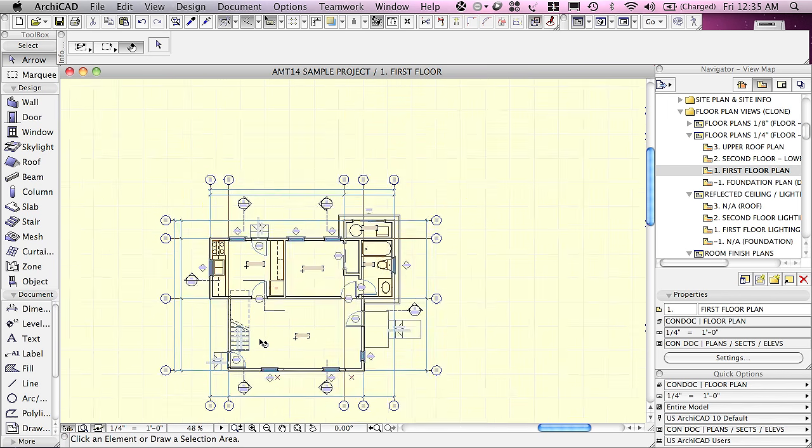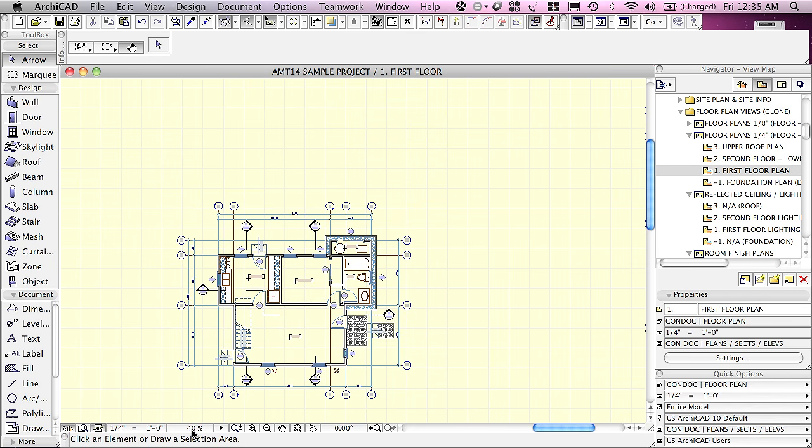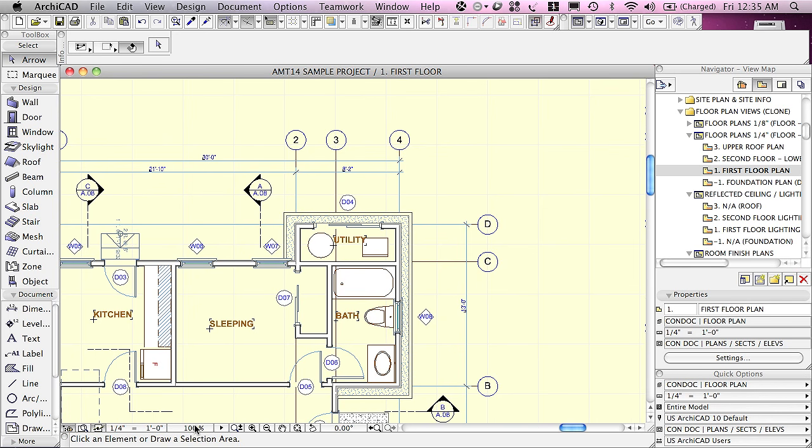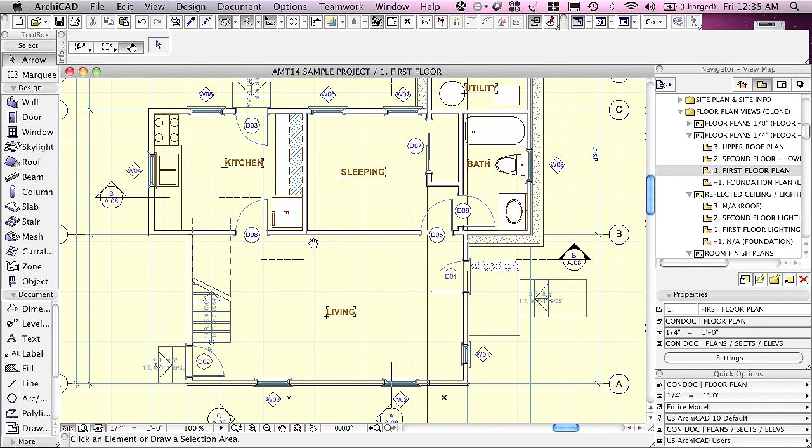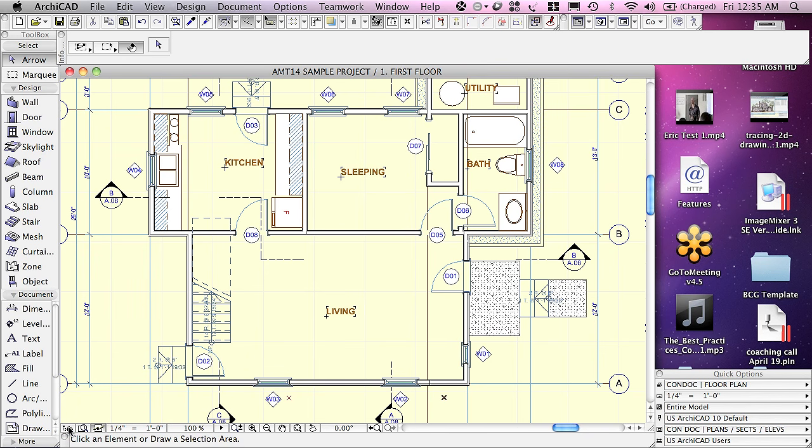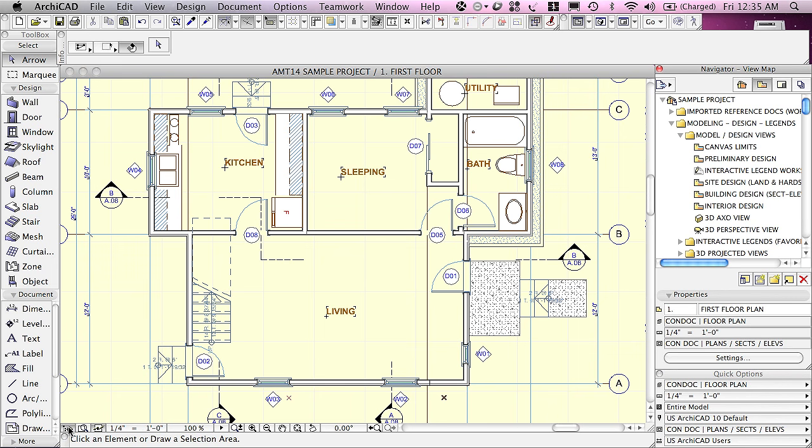And when I zoom in or out, it'll tell me approximately the percentage. So this percentage allows me to see how big the text will be for printing, so I can determine whether something is going to be legible or not. Other controls that are in this area, if I click on this button, it'll hide or show the navigator. So I click again, and you'll see that it pops up in that right side.